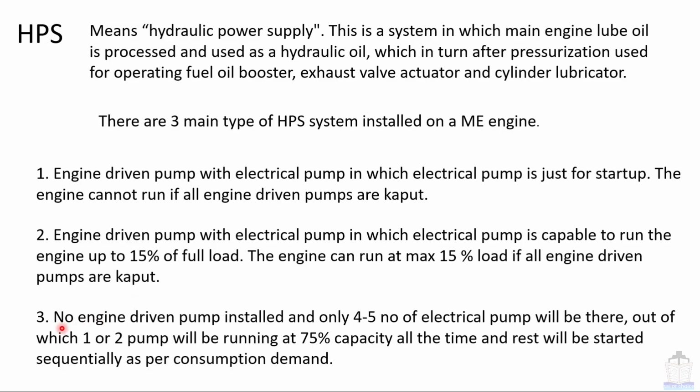And last, third one, no engine driven pump is installed and only 4-5 electrical pumps will be there, out of which 1 or 2 pumps will be running at 75% capacity all the time and the rest will be started sequentially as per consumption demand. So these three types of configuration you will find in the HPS system.